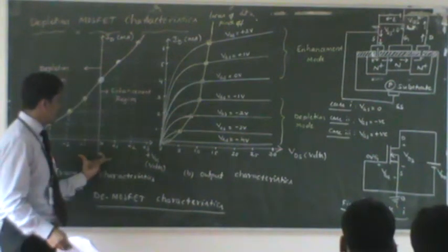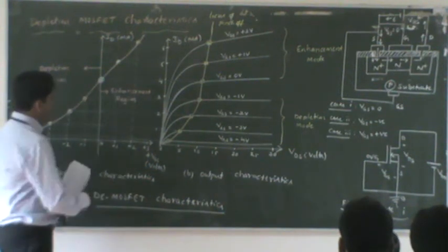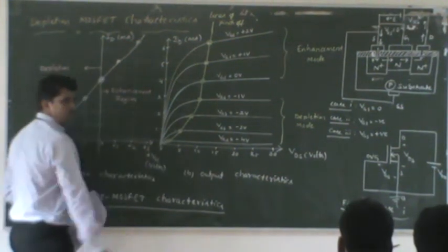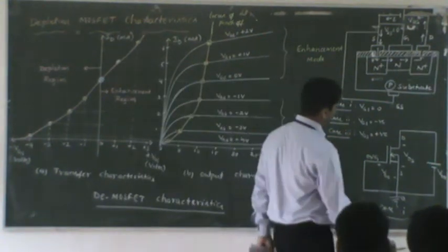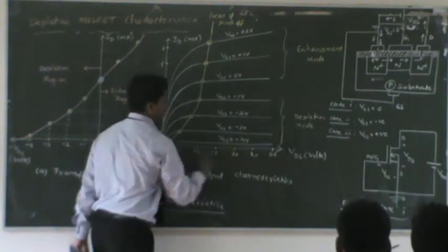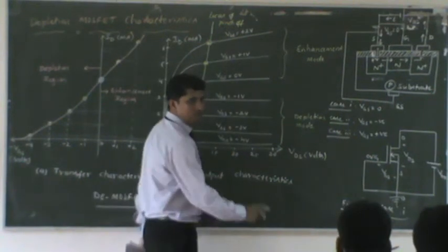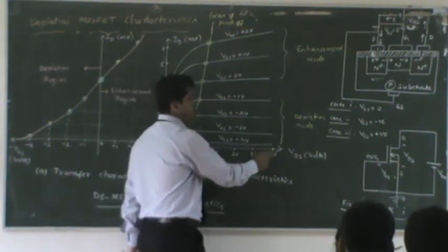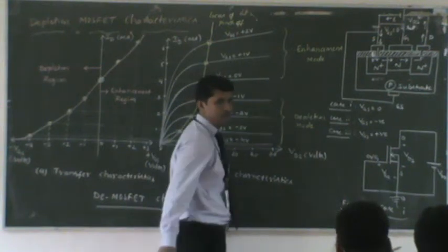Because this transfer curve is with respect to VGS and as well as I. When VGS is equal to 0, we take the first case. So this becomes a single point. Okay. This complete curve here has been transferred. So here what you want to remember is when you make VGS as 0, if you keep on increasing the VDS, initially current will start increasing, but later on current becomes almost saturated. Current will not increase beyond a certain value of VDS. Say for example, if you go beyond 30 volts in VDS, the current will be determined by the breakdown.